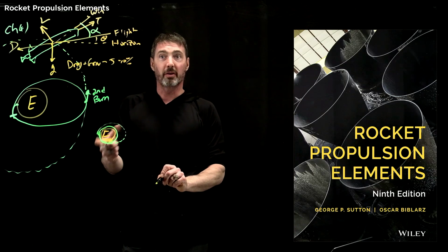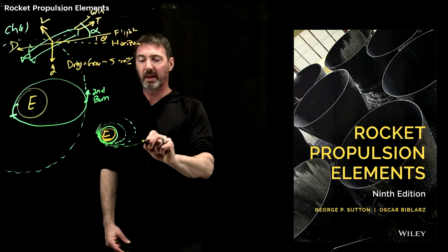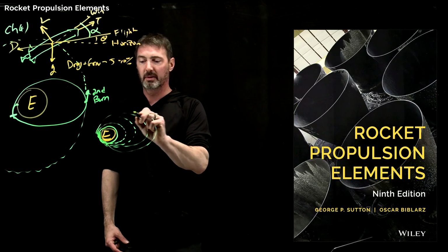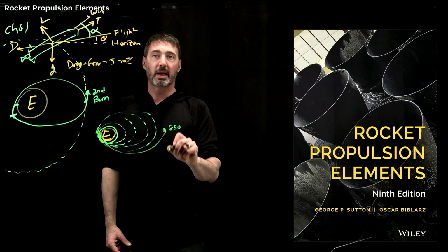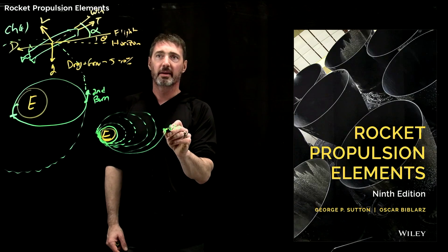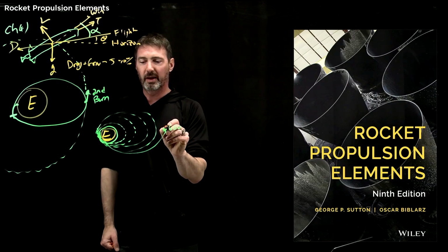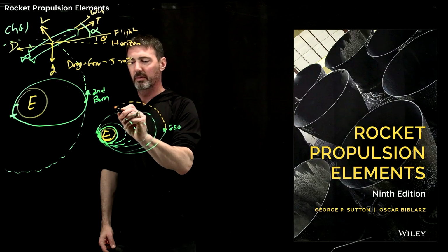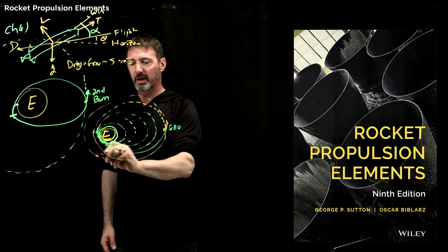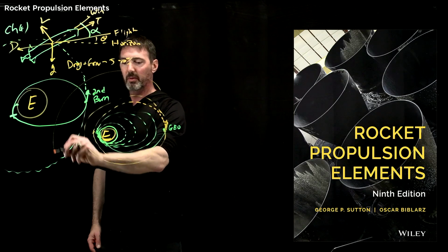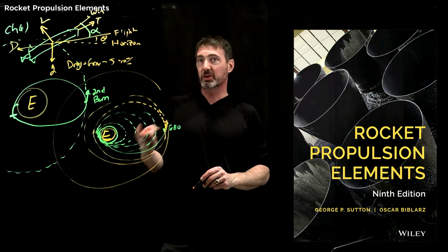Now you're not falling back to the Earth, you're already in orbit. So that would raise your orbit. And then you kick again, and then you would kick again, and then you would kick again, right? And then maybe you kick again. And now maybe this is actually where you would want to be at geo. And then, starting there, maybe I'll switch colors. Then you would kick here, such that instead of falling right back to where you were before, you fall a little higher. Then you would kick again, and you would fall higher, and kick again. And anyways, you get to the point where this whole thing is now circular, okay? So this is actually how you would transition up to geostationary orbit.